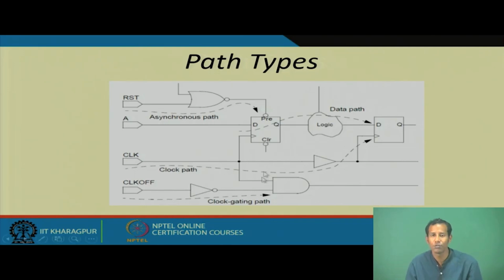So, to reduce this power, we use a technique that if I find any idle state under this condition, at that time the clock will be stopped. If it is in the running mode, or in the wake mode, only at that time this clock will be activated and run continuously. For that type of logic, we need this clock gating path or clock gating circuit, which is useful for low power applications.